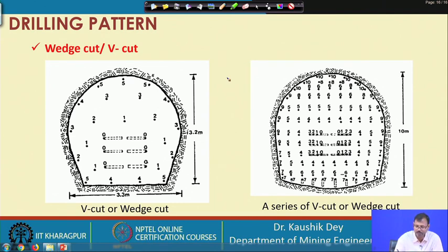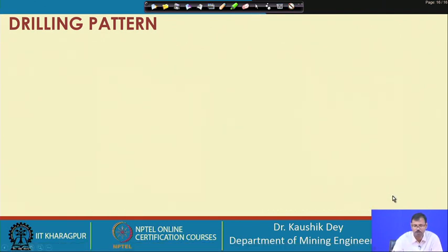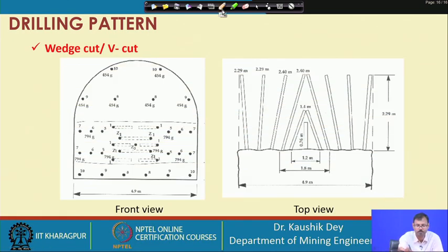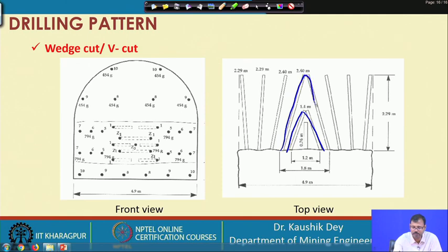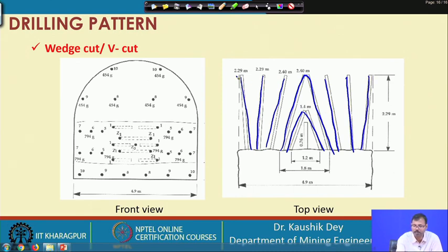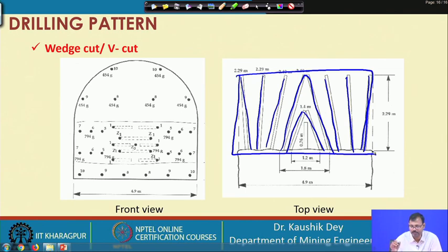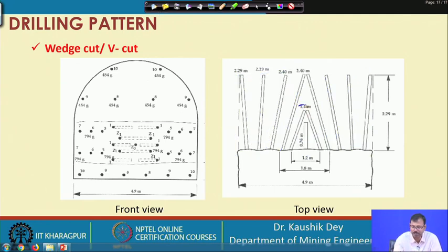So, basically the wedge cut, also called V cut, is carried out to achieve an initial excavation first, then we extend the excavation by the cut spreaders. These are the spreader holes, and finally we are able to achieve a free excavation here. You can see these are different modifications of the blasting. This hole is called a stab hole; these are short length drill holes so that the advancement can be achieved gradually, but this portion may exist or may not exist. We can start with this one also, depending on the type of rock.